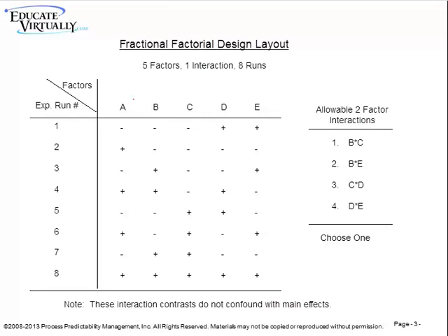Let's get started with our fractional factorial with interactions example. In this case, it's a machining experiment, and we want to increase the tool life. In this particular experiment, we have 5 factors: XY feed, stack height, speed, bit type, and suction foot type. We've already determined that we want to study the combined effect of stack height and speed.